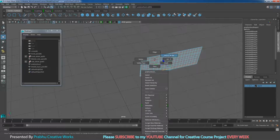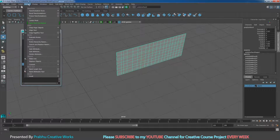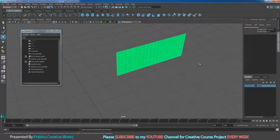So right click and choose object mode. So I will select this object. Now we want to go to modify, convert. Here we need to choose sub D to polygons, poly to sub D option box. Here you need to keep the slider all the way up and choose create.